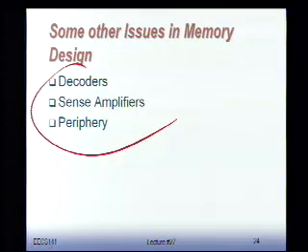So, other work to be done. Actually, there's some very interesting timing issues as well in memories. For instance, sense amplifiers. For those of you who've taken 105, just take 140, you know that for an amplifier to work, you have to have current flowing through it. Now, can you imagine those amplifiers in there burning current all the time? That's a lot of power. We don't want to do that. So sense amplifiers, we're only going to turn on for a very short time.